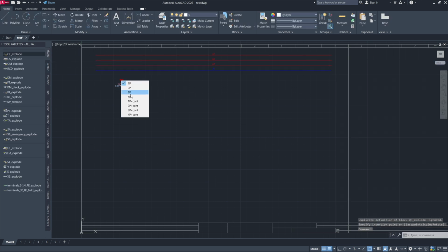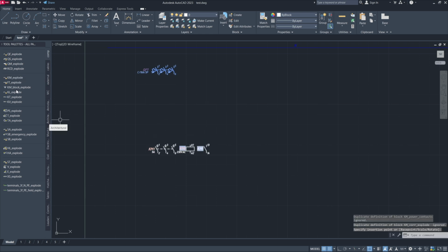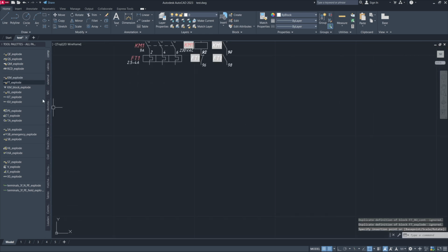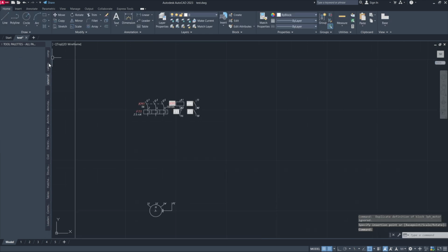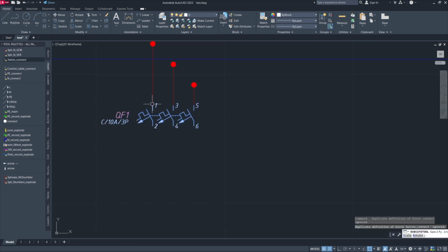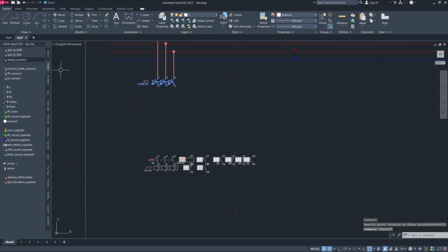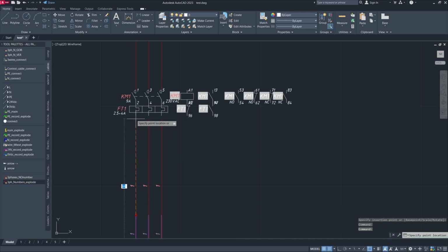First, we are using a drag and drop approach to place components onto the drawing from the Tool Palettes tab. This tab can hold an unlimited number of blocks, primitives, or commands. These items are stored in a separate file, so they don't take up space in your current drawing. AutoCAD just references them by path. You can save components from my library into the tool palettes or create your own.